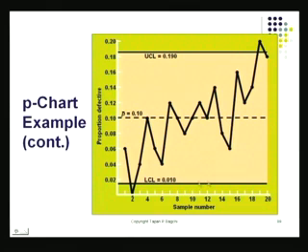Well, when this was done, you had a suspicion that perhaps 18 defects were too many, right? When you looked at the 20th sample. And see what they found? They plotted the P chart with the upper and lower control limits as calculated. And after plotting the chart, they did find that in this zone the chart went beyond the control limit. So this is an opportunity for finding the defect, the issues, the problems there.